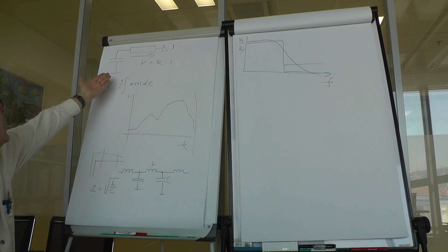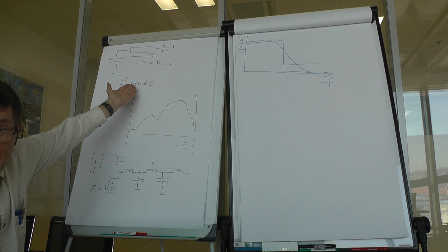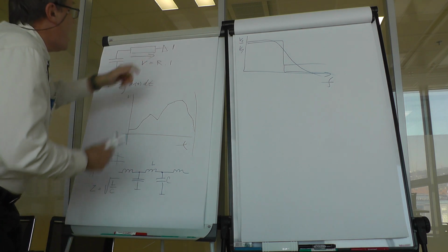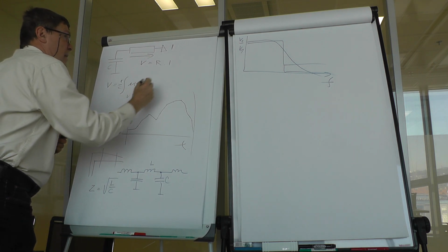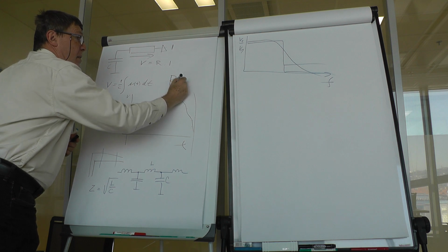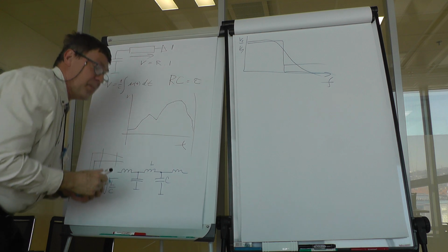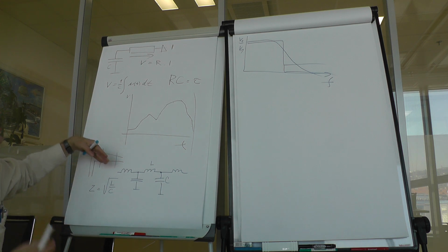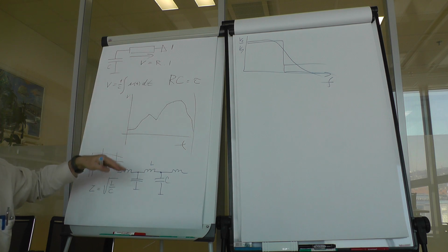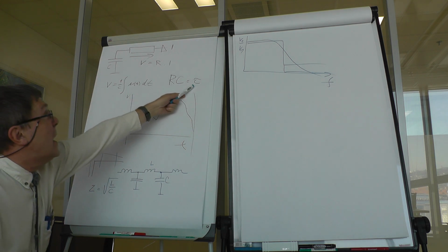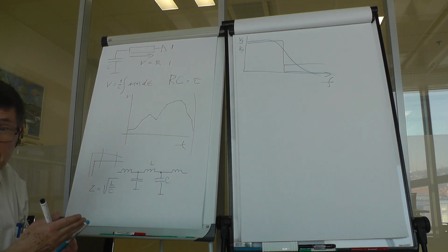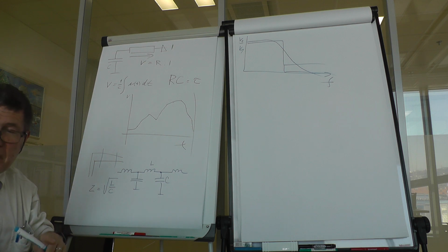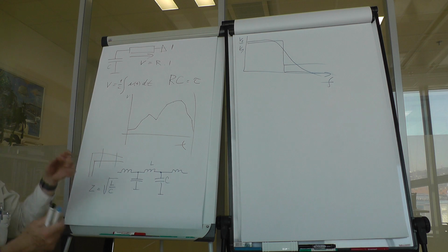And for this circuit, if that was a linear one, you would possibly consider that there is a time constant R times C, just if you, for example, start to charge the capacitor through the resistor, this is the element which would govern the exponential behavior. Within the tau time, you would get from 0 to 63% of the full voltage, and so on.